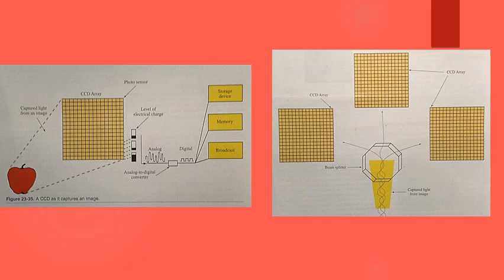Digital camera technology. Traditional analog televisions use vacuum tube imaging to capture images, while HDTV uses the charge-coupled device, or CCD. The charge-coupled device, CCD, is an integrated circuit consisting of an array of photo sensors that convert light from a camera's focused image to electrical energy. See figure 23-35. The level of electrical energy is directly proportional to the level of light captured by the photosensors.